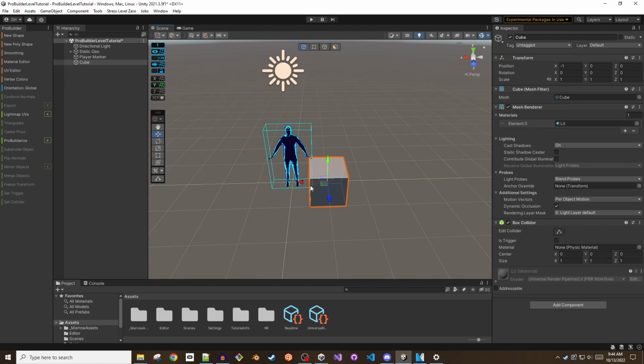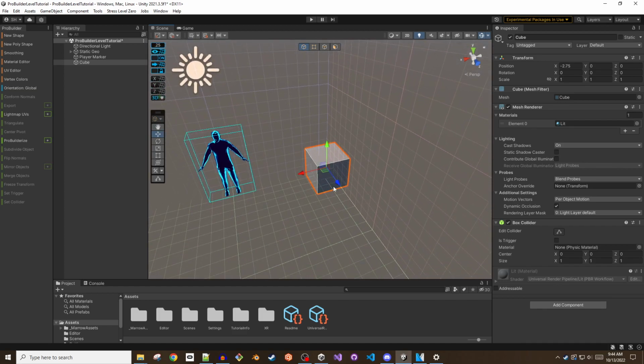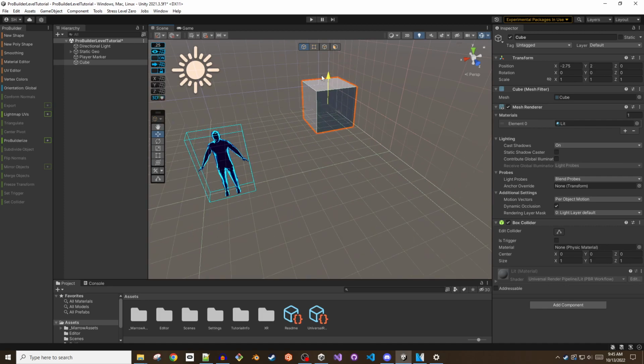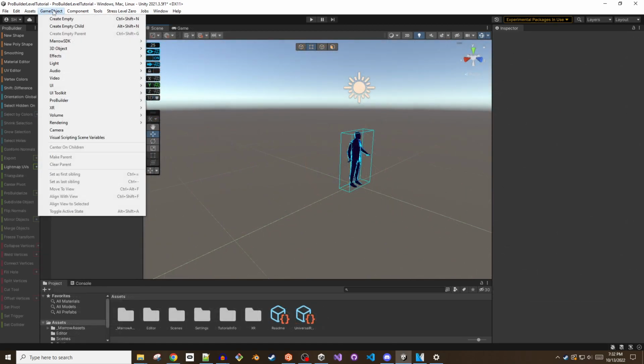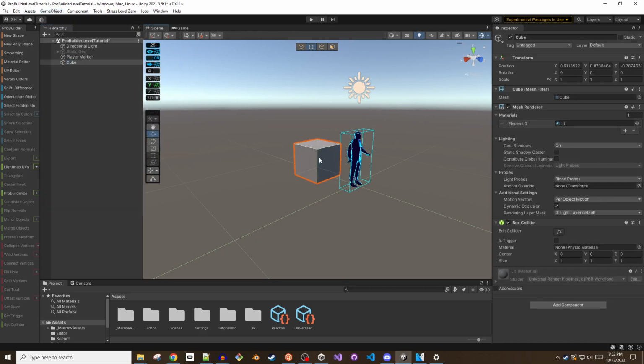Whatever grid solution you choose, enabling grid snapping will save you endless hours of frustration and tedium because you will not be fighting the sloppiness that comes with just eyeballing whether or not two meshes are lined up. You will know it thanks to the grid snap. Also, if you're building something indoors, there's usually an expectation that floors are level and doorways are more or less properly aligned. It's important to note that ProBuilder operations only work on ProBuilder geometry.